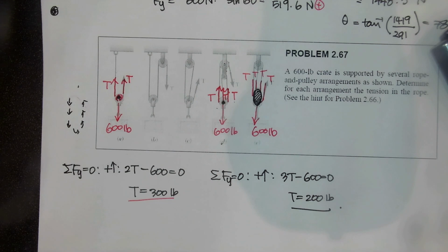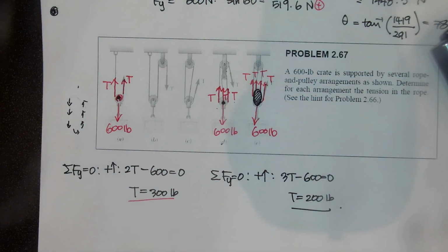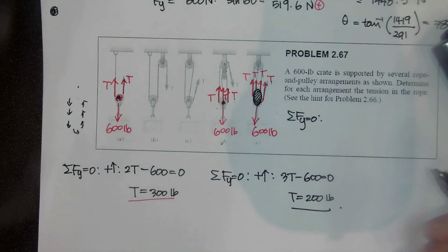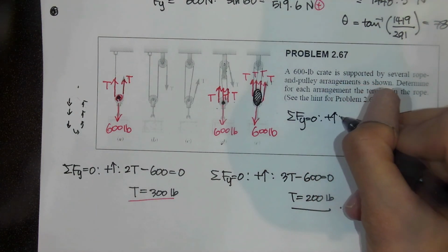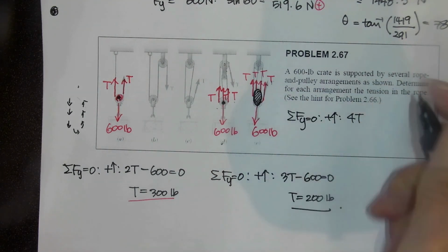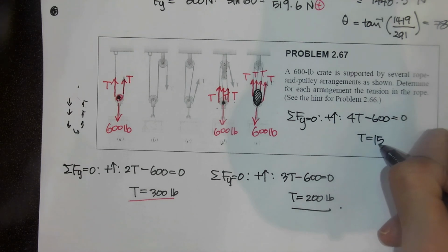So magnitude is the same, T, for 4 segments. And then cable tension is away from the node now. Right? And then the equilibrium equation about y direction, 4T upward, 600 downward, so T should be 150.